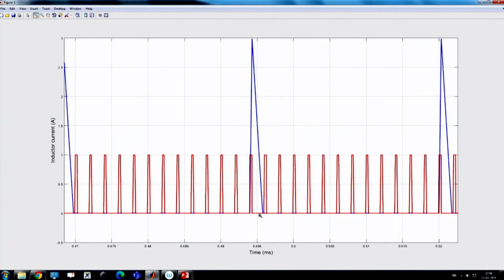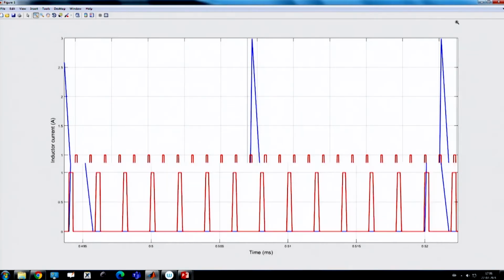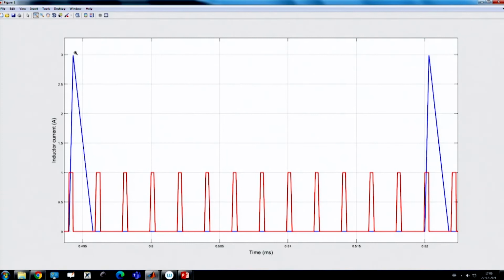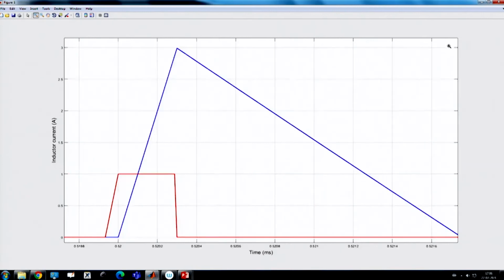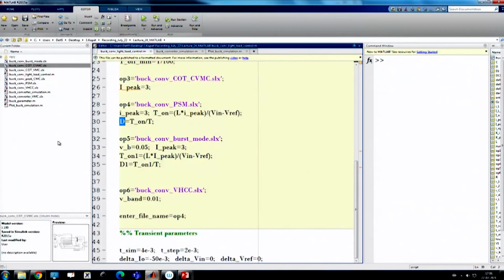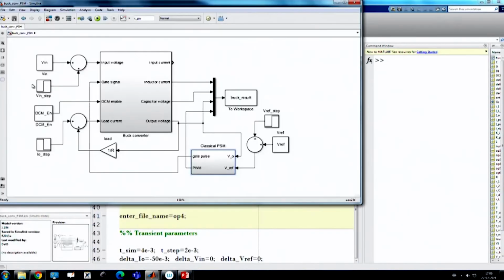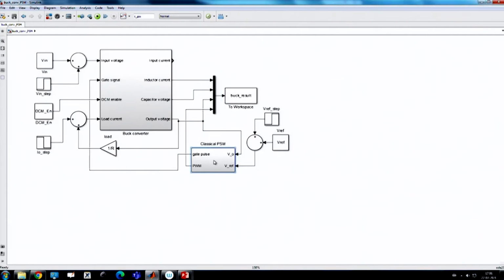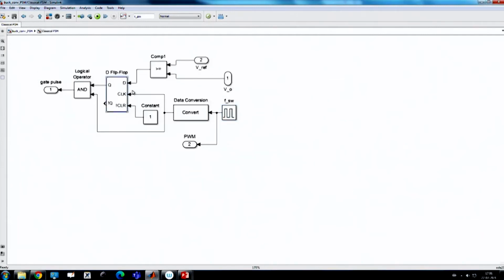So that means, between the two, here we call it a charge pulse. It will turn on for 1 cycle and go back to 0, and then the inductor current will decay, and the switching clock will be skipped for this entire duration. Again it will be activated here, because this logic is coming from this PSM logic, from this D flip flop, which we have discussed, and we are going to check.